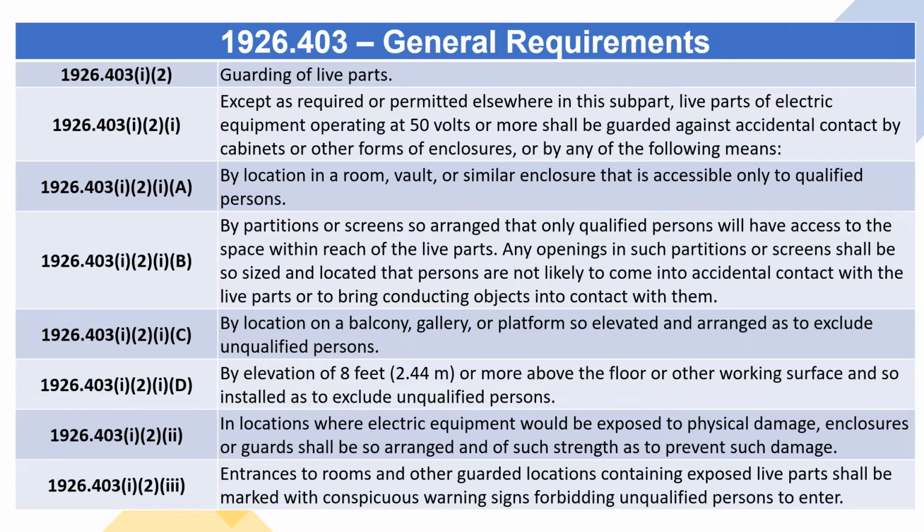(B) By partitions or screens so arranged that only qualified persons will have access to the space within reach of the live parts. Any openings in such partitions or screens shall be so sized and located that persons are not likely to come into accidental contact with the live parts or to bring conducting objects into contact with them.